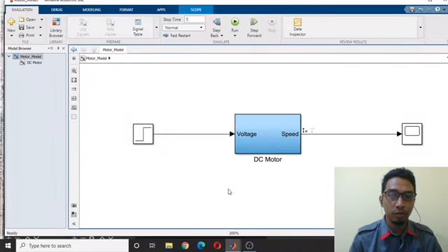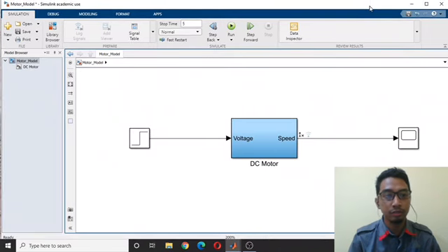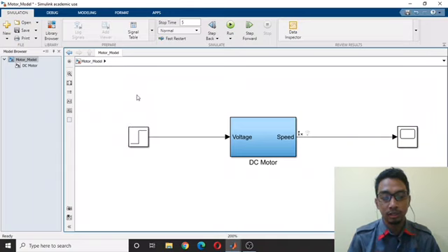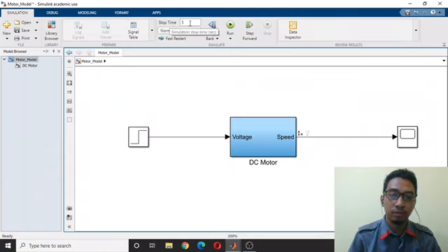Okay, next we want to have a step response graph using Simulink simulation. From the existing block diagram, we can add a step input and scope from the library, from here. Double click on the step and set step time to 0, stop time 5 seconds, and then click run.